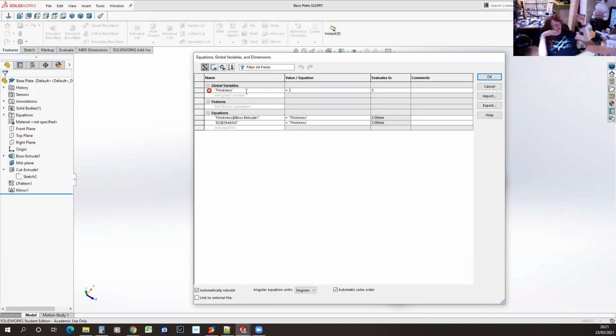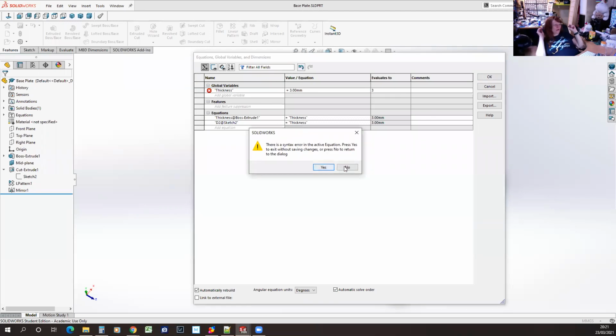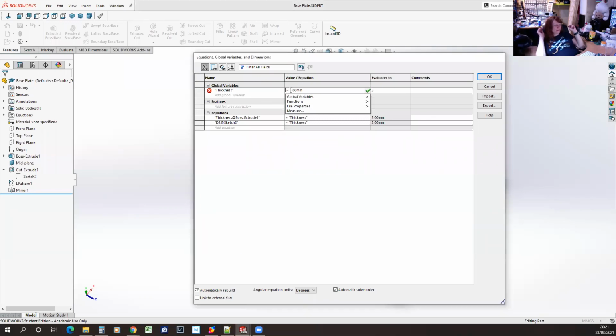Well, I tried it here just now, and I got the same thing, but when I did it again, I didn't put any spaces in the equation box, not between the equals and the 3, not between the 3 and the mm. That one worked. It puts the space in for me. Yes, just take the space away, and then try to confirm. Now hit the check mark.